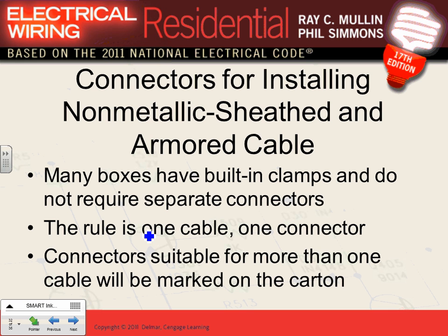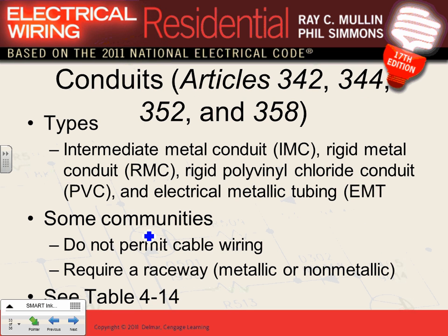A couple of rules, guys, about boxes, about connectors for installation. If you have a metallic box, again, this is for the project managers only, every cable has to land under a clamp. Unless the clamp is rated for 2 cables, you have to land a clamp per cable. Clamp per cable. So that's what they're saying here. Unless they're rated for more than 1.